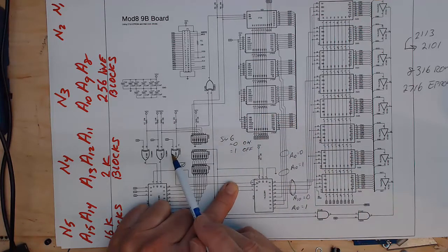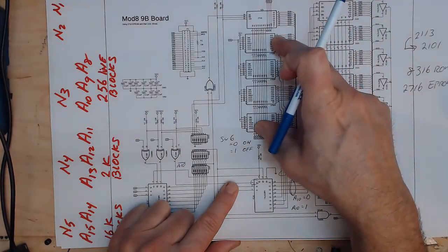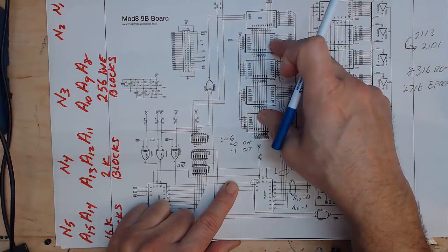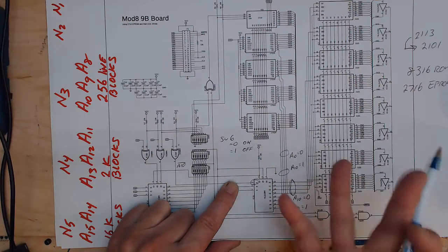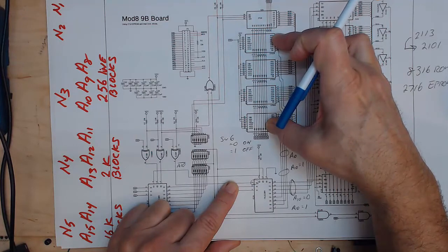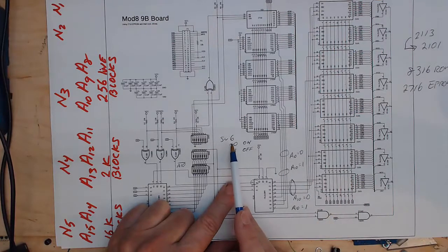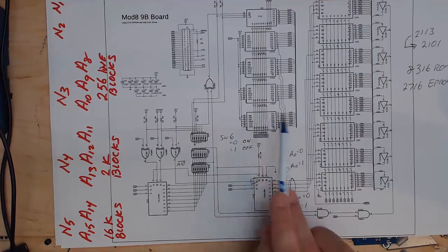So in its natural order with switch 6 on, and so that is set to 0, so this is not inverting, the natural order puts the RAM on the bottom and these EPROMs on the top of our 2K block. So this is the bottom 1K and this is the top 1K. If we switch this and we turn switch 6 off, it flips those over. So now our EPROMs become the bottom half of our 2K block and our RAM becomes the top half of our 2K block. Okay, so that's what switch 6 does in this switch 3 bank. It inverts which of those two are on the bottom.